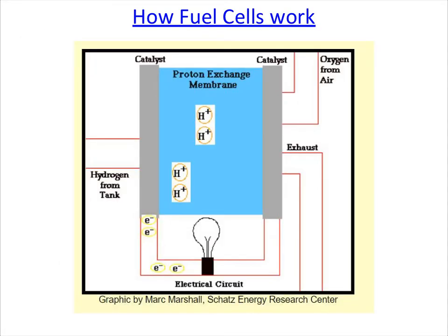So that it's easier to understand exactly how a hydrogen fuel system works, for you visual learners, I provided you with this picture of exactly how the chemical process works. As a reminder, a fuel cell is composed of 3 main components: an anode, a cathode, and an electrolyte membrane. The magic of the PEM fuel cell is in its proton exchange membrane, which again looks like a piece of construction paper. And it works by passing hydrogen through the anode side and oxygen through the cathode side.